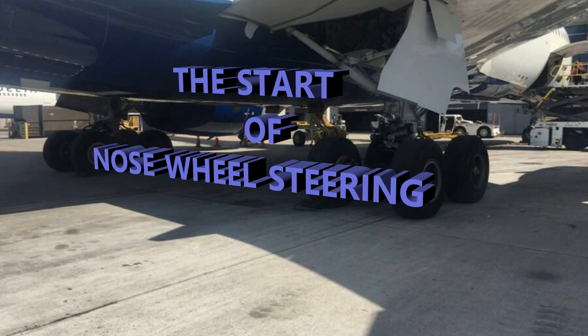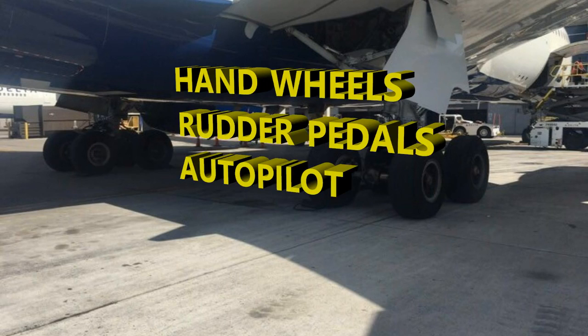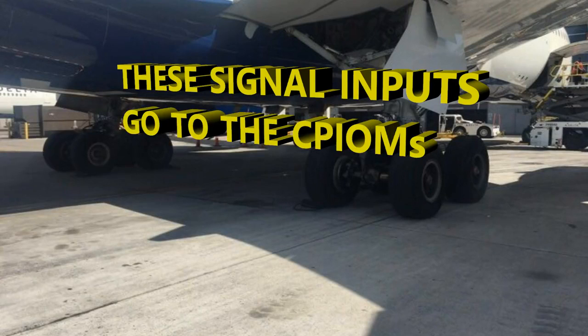Those are coming as electrical signals, your steer by wire. Your inputs are coming from rudder pedals, your autopilot, or your hand wheels, and those signals are going to be picked up by the CPIOMs. That's the wheel steering control system application of those CPIOMs, calculating and monitoring those commands as well as any feedbacks.